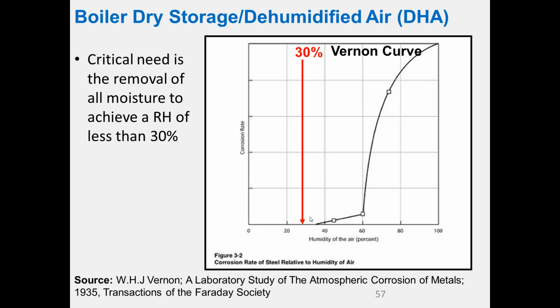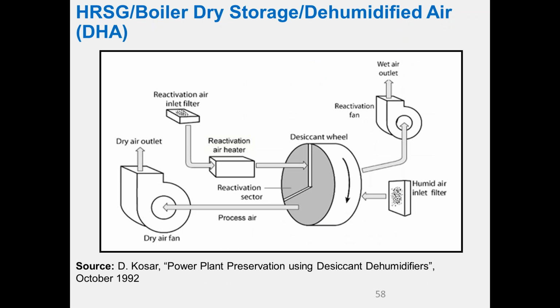And basically you can say that the boiler is now in suspended animation, and there should be no corrosion occurring. Okay, and a dehumidifier is normally Munters dryers, but this is what they look like on the inside. You have a self-regenerating desiccant wheel. Okay, so we're bringing in,